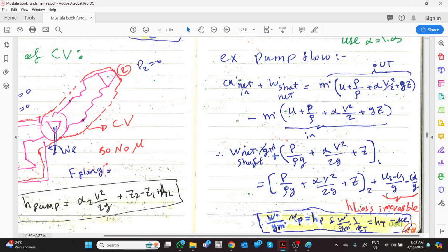And this one we name irreversibility, which is the irreversible work that has been done, which you can never gain back again. It is gone, but it was injected inside the fluid, and we also name it H loss. So we can write it like this: that is the work multiplied by eta, the horsepower or whatever we are going to have. And for the pump, it's the head of the pump. So if I take work divided by g m dot, it is head.